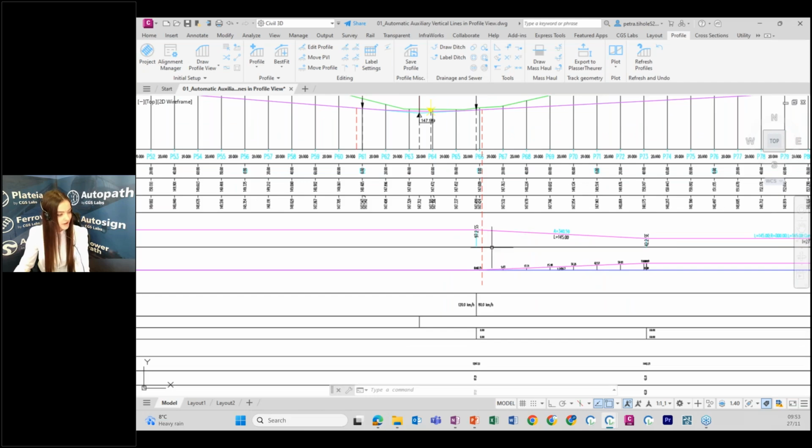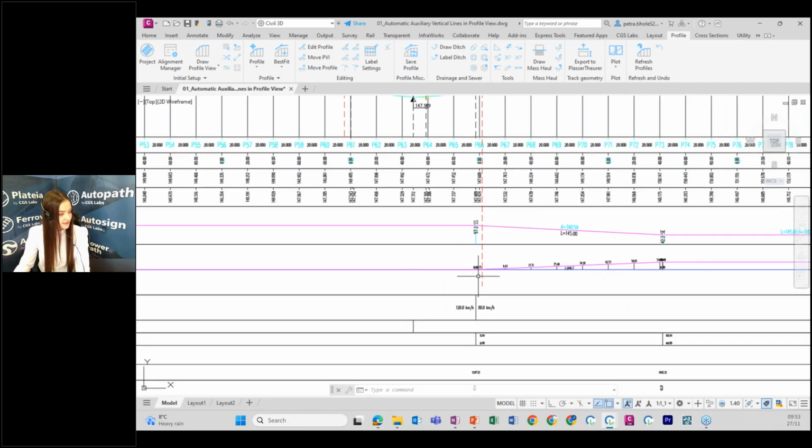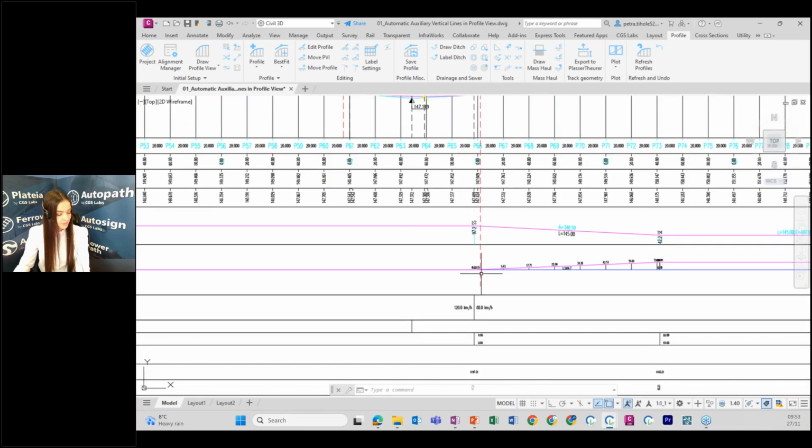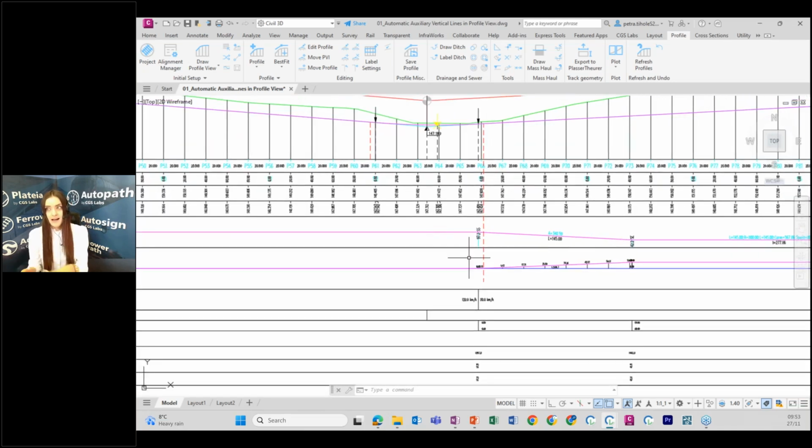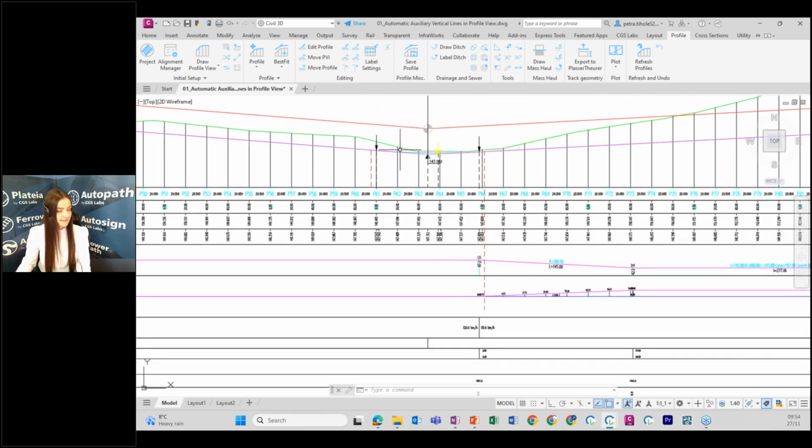Here I have the spiral in the layout. And you can check that I'm in this restricted area where I'm limited by what elements I'm using. So let's say that this is not okay. I want to move my profile view a little bit to the left.